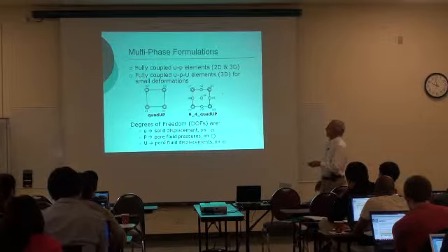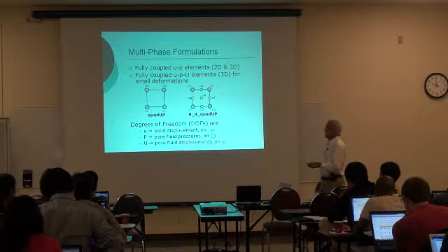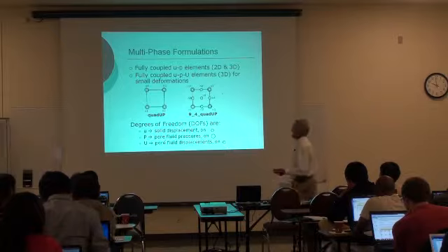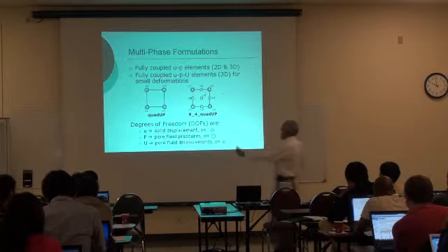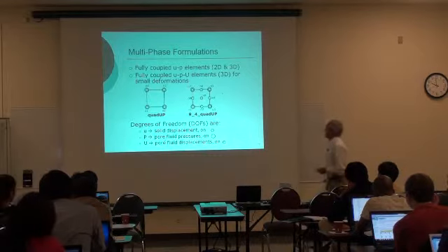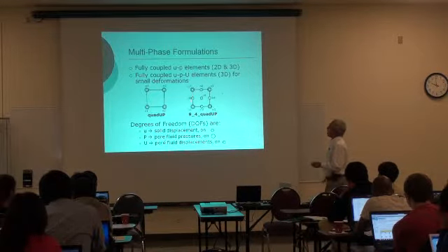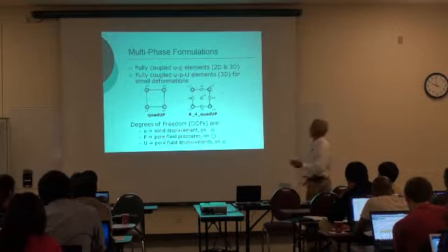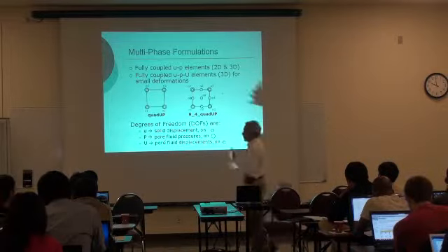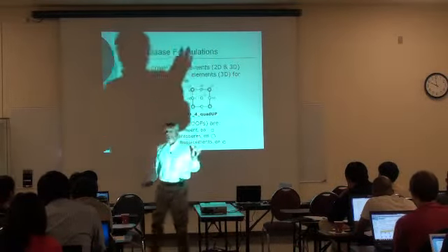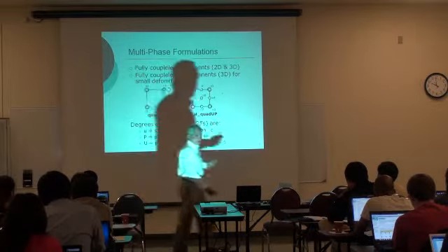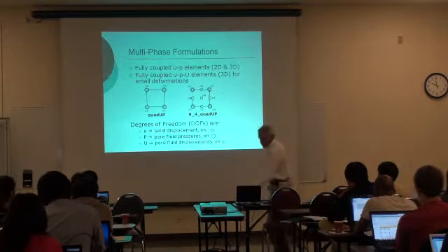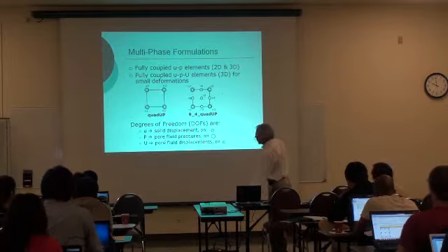This element, when it is presented like this, is not stable. So that's why in OpenSees you have what is called the 9-4 quad UP, where the displacements are recorded in 9 nodes, and the pore water pressures are recorded only in the vertices, in 4 nodes. Okay, so this is a stable, an unconditionally stable element that you can use.